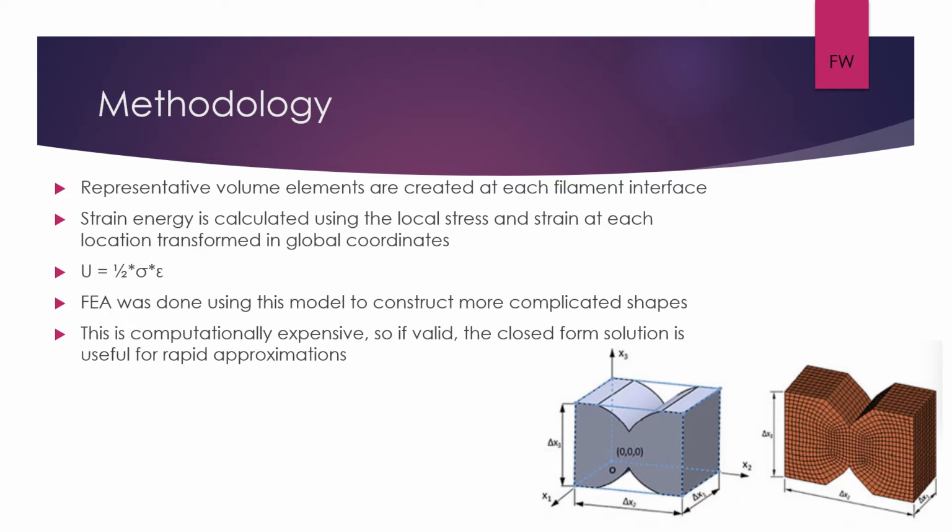Finite element analysis was done using this model to construct different complicated shapes of which the mechanical performance was of interest. This is computationally expensive, however, so if valid, the closed form solution of classic laminate plate theory is useful for rapid global response approximations.